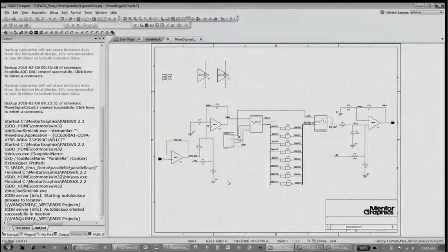But another question is being able to export 3D data from our tool with model information. This is supported now, so I can export out a STEP model of this entire board with all of the STEP models included. It actually comes over into the MCAD tool as an assembly, which is kind of cool.